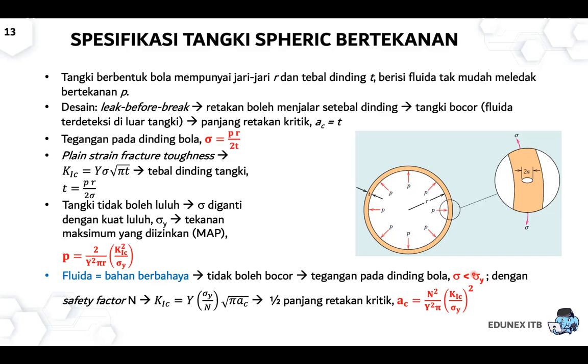So as long as the crack that we found is less than the critical crack, we can say the equipment is fine. However, if we find that the crack is higher than the maximum, we will say that the equipment is not safe. Because at some time there would be a crack and a leaking, and after that there would be a break.